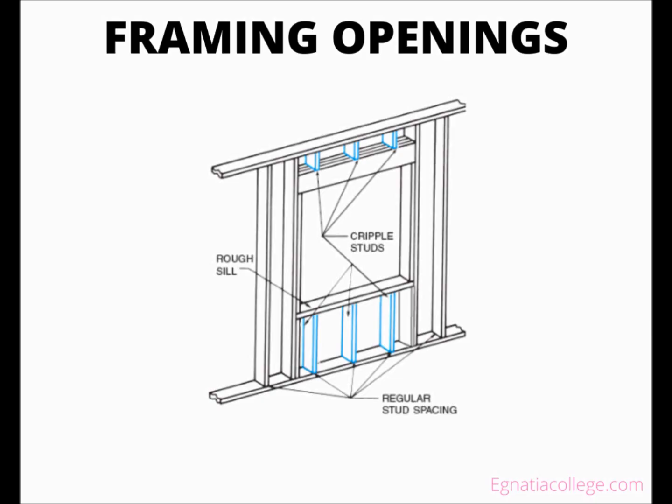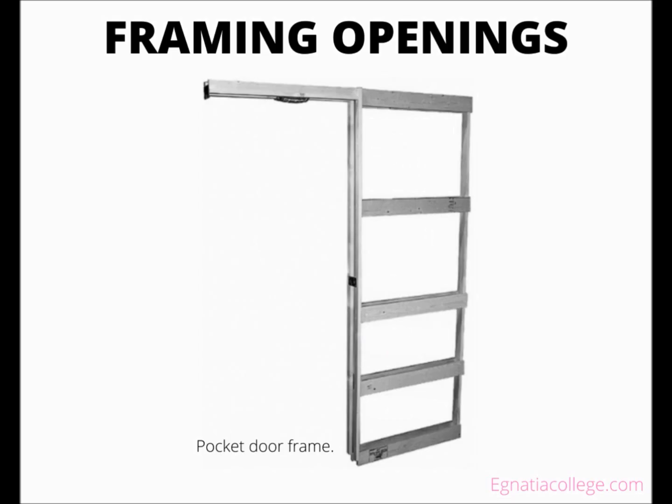Pocket doors are sliding doors that slide into an opening in the wall, thereby allowing the largest possible opening without swinging into the room. Most builders install pocket doors as a pre-assembled frame. The wall framing to provide the opening into which a pocket door assembly can be installed is generally the same as the framing for any other type of door. Pocket door manufacturers provide rough opening dimensions for their products.